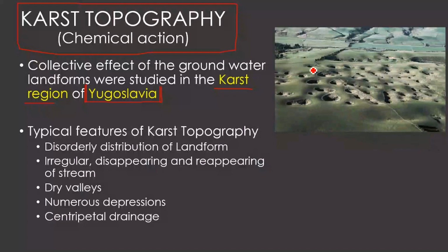Okay, so this is an indication of the underground cavities, or the erosional properties of the groundwater. As a result, if you have not taken proper care of this, and you are just leveling the surface and making it horizontal, and you construct a building over it, what happens to this building? That will lead to the failure of the structure.